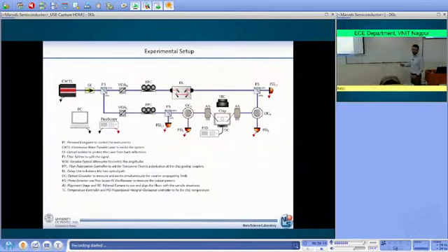We have a tunable laser, a laser by which you can change the wavelength. Then we have an optical isolator, which is used to prevent back reflection from entering the laser and rendering the laser unstable. Then we have a fiber splitter: everything is in fiber, so where you would have a cube beam splitter, in fiber you need a fiber beam splitter.